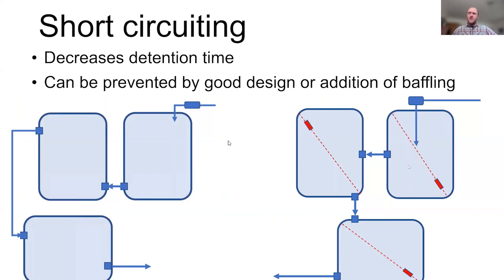So it makes it utilize the full surface area of that lagoon. So if you're experiencing poor lagoon function, and this might be a problem, this could be really helpful to address this. And you can figure this out numerous ways. You could put some dye in there, but I've seen a lot of people put oranges in there. So just dump a crate of oranges where the water is flowing in, and then just see where they float, see where they go. And if they go just straight towards the outlet, then you know you have some short circuiting issues.